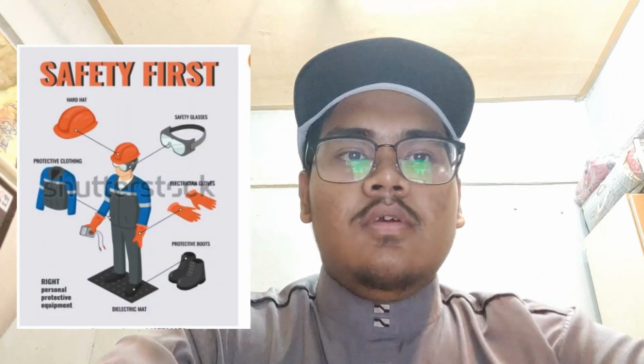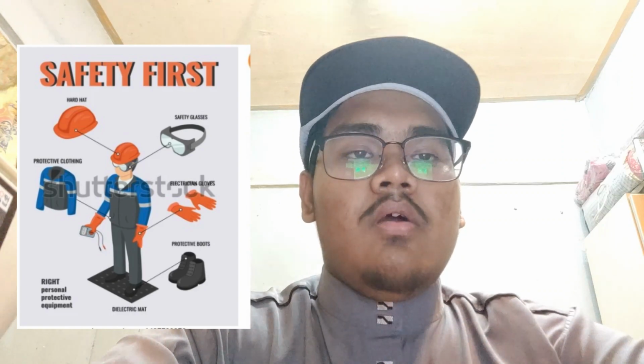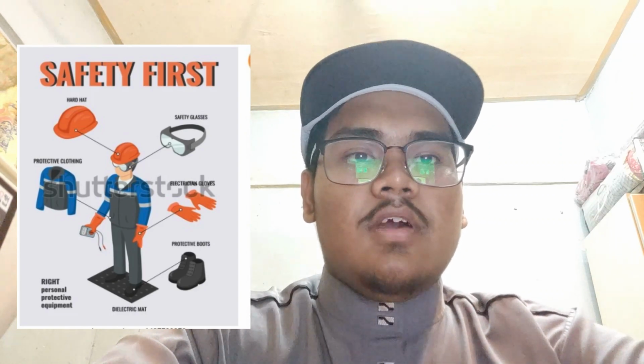In this video, I will explain the procedure of the milling process. Before starting our work, make sure to wear all the safety gear, because safety is our priority. For the milling process, the student will be provided with a raw workpiece. The first step is using a vernier caliper, measure the workpiece according to the size given and mark the excess part to be milled later.